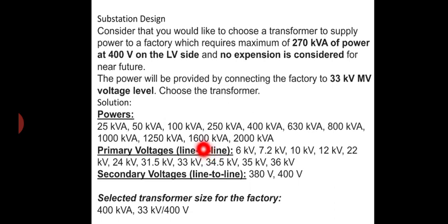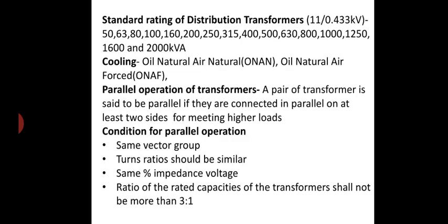Okay, next we need to choose the transformer. The power in terms of kVA is 270 kVA. The available ratings start from 100 kVA, 250 kVA, and 315 kVA is also there. But you cannot choose 315 kVA here.